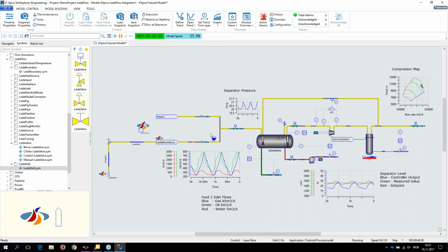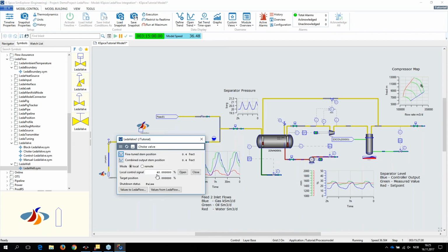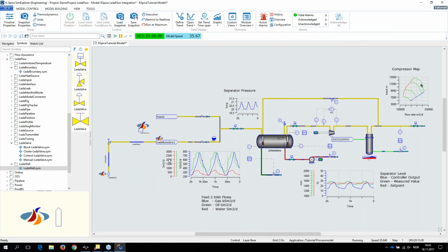I'll now transition the system into a non-slugging state. So remember, these slugs are appearing because of a too low velocity in the riser. So we'll increase the flow rate coming from the well. We'll step this up to 60%. You will then see that the slugging behavior will continue for a little bit before it settles out and eases into its new position.